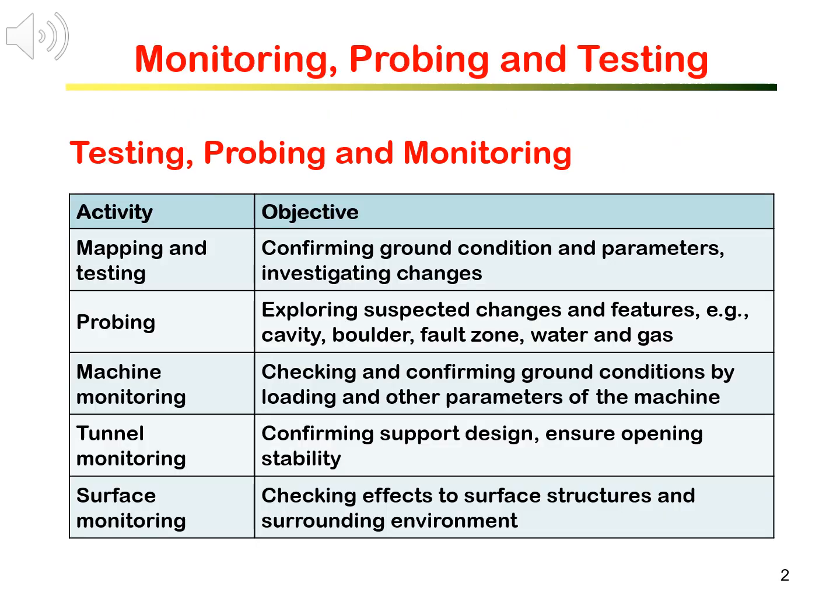During underground excavation, there are a number of activities associated with understanding the ground in order to improve the design and construction. Those activities include mapping and testing to gather more detailed information of the ground at the excavation location and depths, to verify and update the information obtained from earlier stage of site investigation.